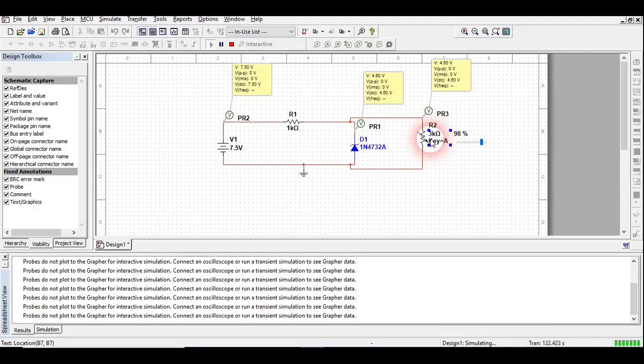4 to 5 observations means that you increase the resistance in such a way that this Zener diode reaches its breakdown voltage. Afterwards take 3 to 4 observations of different resistors, in which you will show that this voltage is not changing across the resistor. If you are going to take pictures, it would be simple.